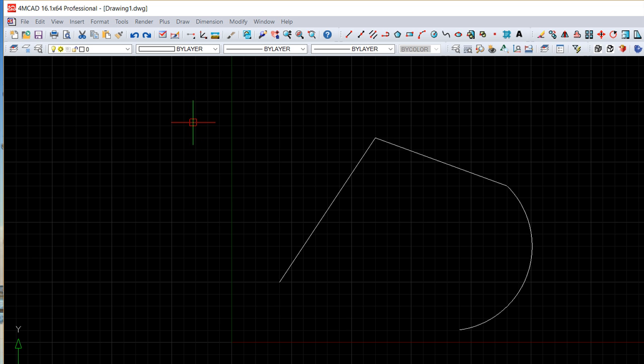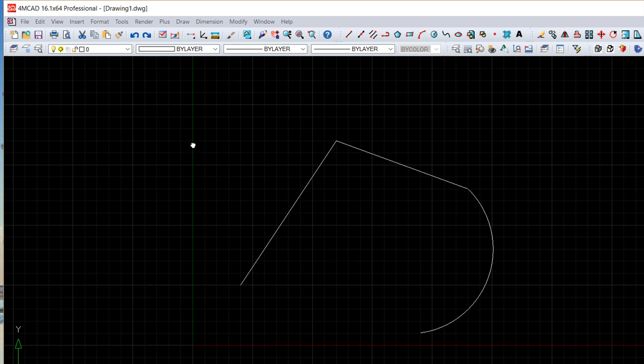Entities such as rectangles, polygons, and donuts, as others also, or in 3D, can be edited with the polyline commands. And we can edit this polyline by opening, closing, changing widths, changing vertices, changing the shapes. There are a lot of things we can do. Let us see a couple of examples.